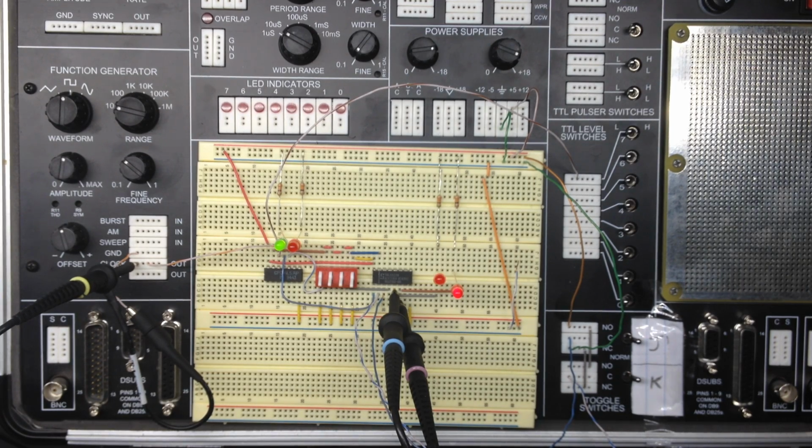In this lab, we were asked to demonstrate the functions of a D-type and a JK-type flip-flop using a 74LS74 IC and a 74LS112 IC. The circuit that you're currently seeing is a little bit different from how the lab asked us to set up. We were asked to set the lab up with one circuit at a time, but for the sake of the video we've set up both circuits on the same breadboard, sharing a clock so that we can see both happen at the same time.